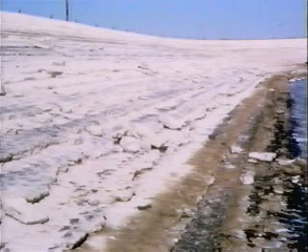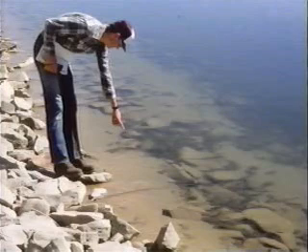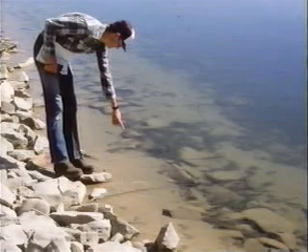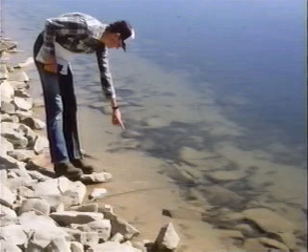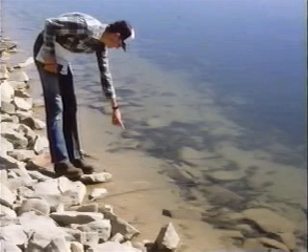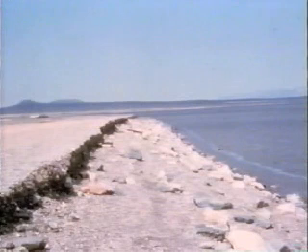Now, let's see some samples of sites where slope protection has broken down. On the upstream slope, a common problem is beaching. The term beaching is used to describe the condition that results when part of the upstream slope is removed and deposited farther down the slope. First, the slope protection and eventually the embankment material is removed. A flat area, the beach, remains along with the steep back slope. The steep slope is called a scarp.